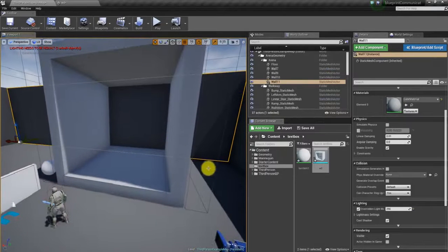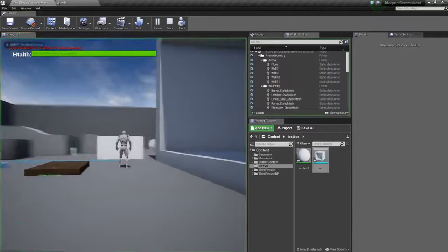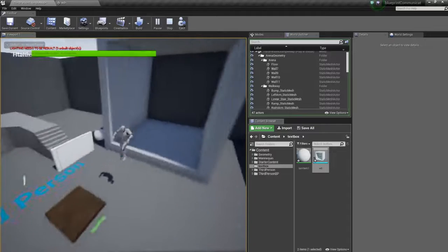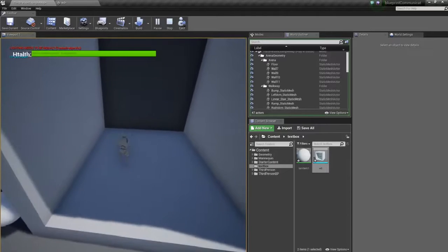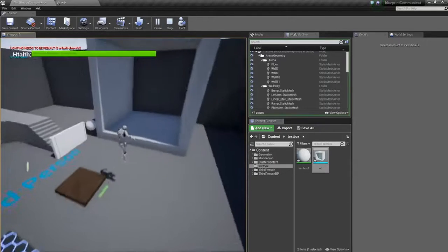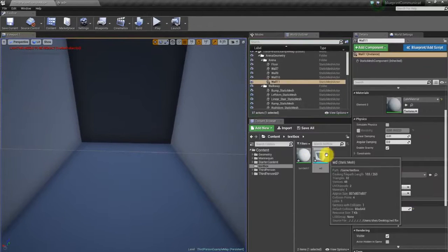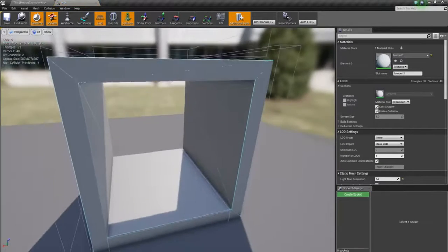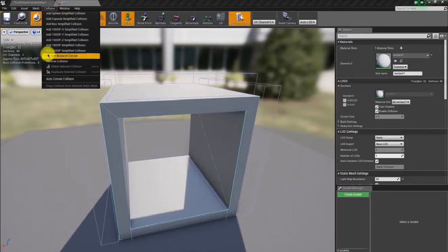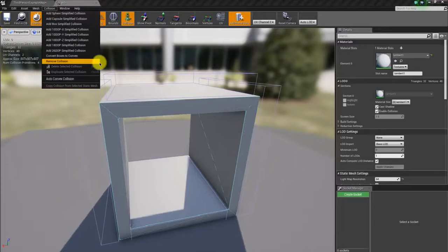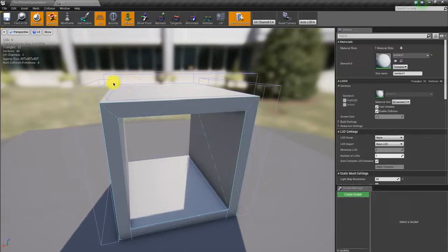To overcome the shortcomings of the discrete collision detection algorithm, the continuous collision detection algorithm models the motion process of the model, constructs a continuous motion path, and then judges the collision situation between the models based on the path. Through the use of the user interface or the dynamic simulator, we determine the motion interpolation between several locations, reducing the complex motion process of the model to a series of simple rigid motions.